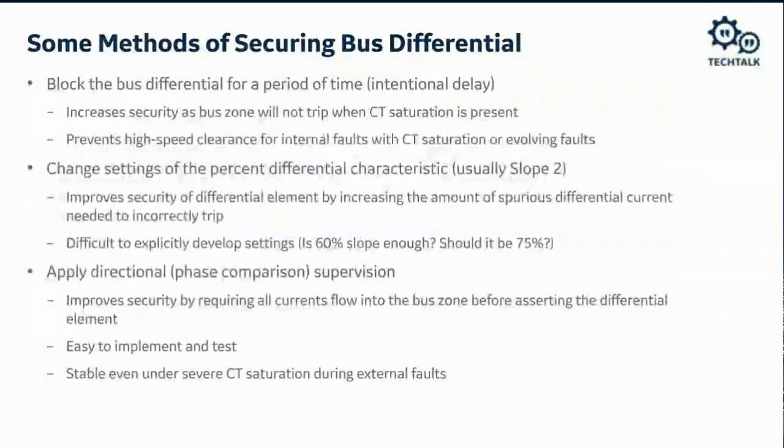Some of the methods of securing bus differential. We won't talk about the intentional time delay because we mentioned the disadvantages of using that. We talked about the dual slope characteristics. One other principle we'll talk about is the directional principle.